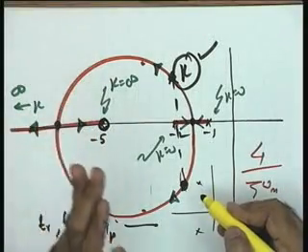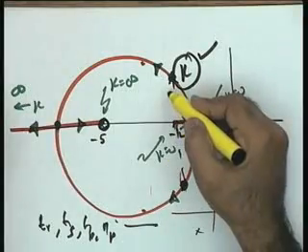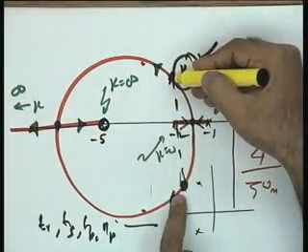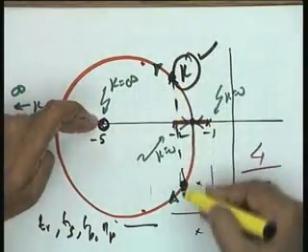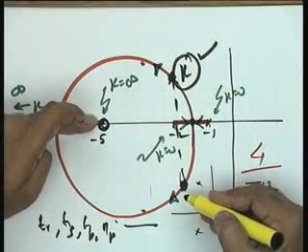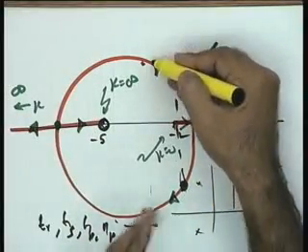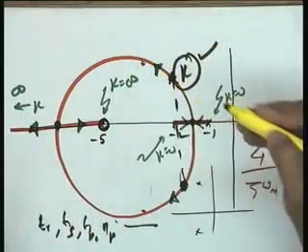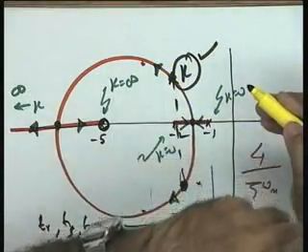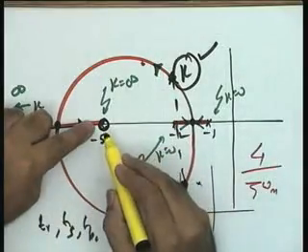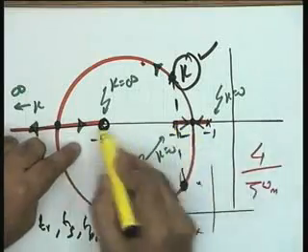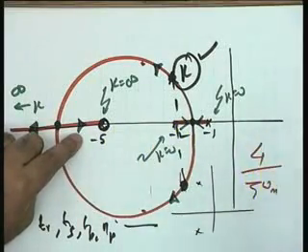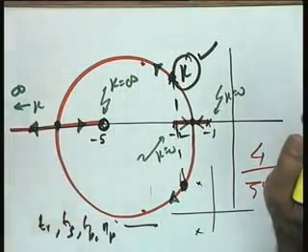This zero is going to give you a peaking effect early. So in that particular case, please tell me whether you will pull your roots this way or this way to account for the effect of the zero. These are the closed loop poles. Which way would you like to pull? You want to see the effect of this s equal to minus 5. If it is close to this particular point, it is going to give you more peaking phenomena, that is, it is going to give you a pronounced peak.